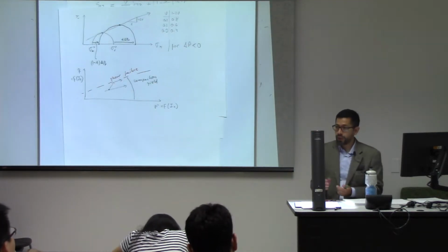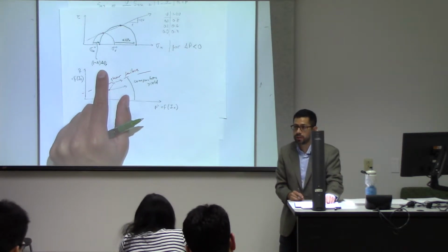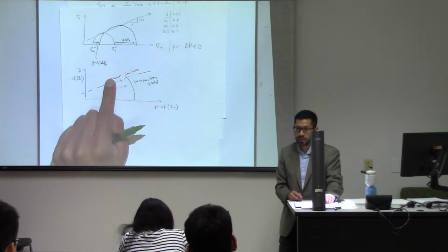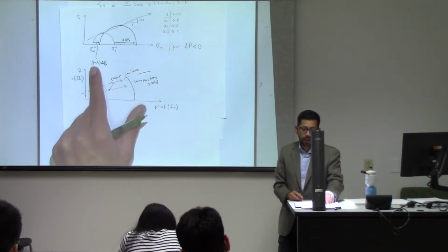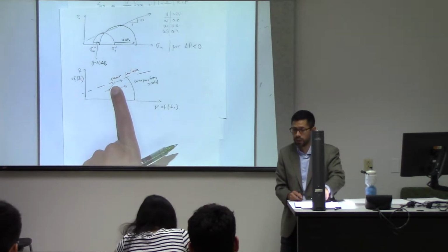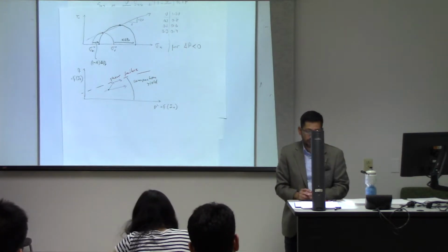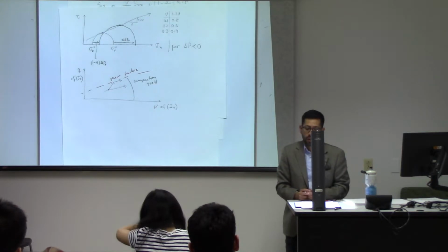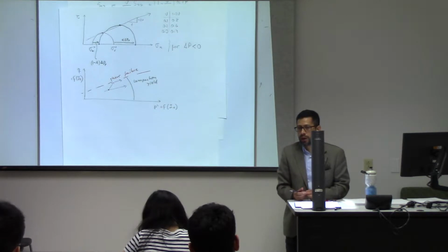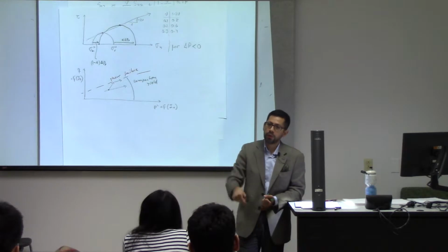So now with these equations, we know we can calculate how much effective stress is going to increase and how much total horizontal stress is going to decrease. Knowing how much effective stress increases is going to let us know, if we know what kind of material we have, if we go into crushing, or if we go into shear failure. Crushing most times is not going to be good because if you crush grains, if you crush the rock, permeability is going to go down.